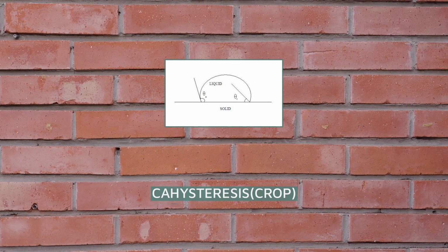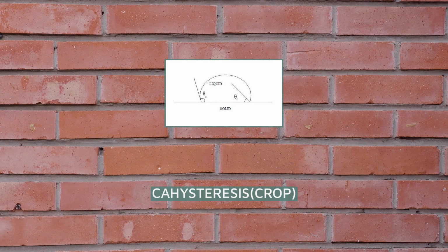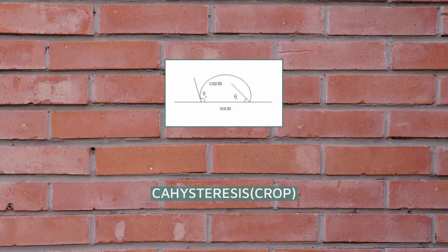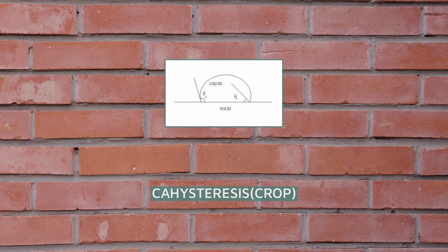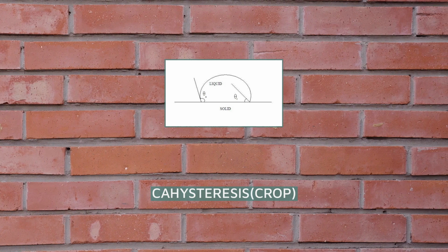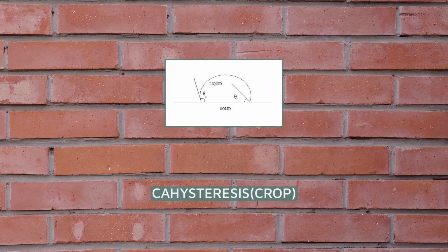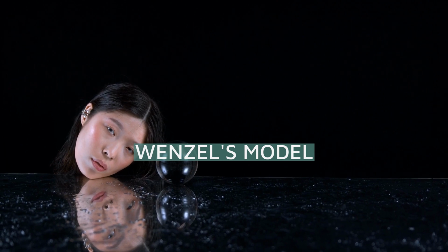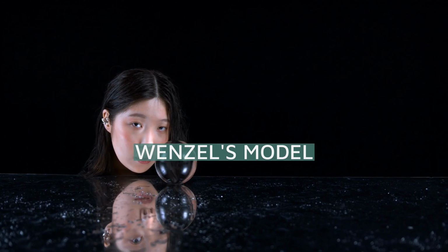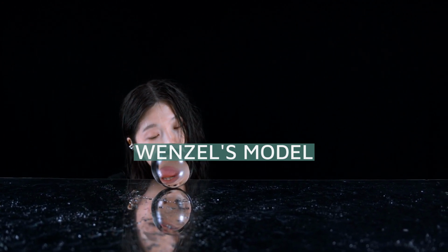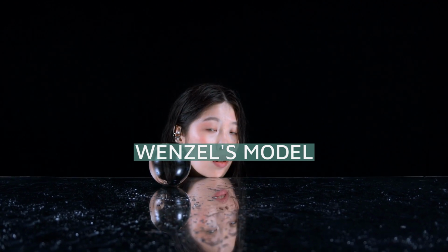Such surfaces have varied effects on the contact angles of wetting liquids. Cassie-Baxter and Wenzel are the two main models that attempt to describe the wetting of textured surfaces. However, these equations only apply when the drop size is sufficiently large compared with the surface roughness scale. When the droplet size is comparable to that of the underlying pillars, the effect of line tension should be considered.